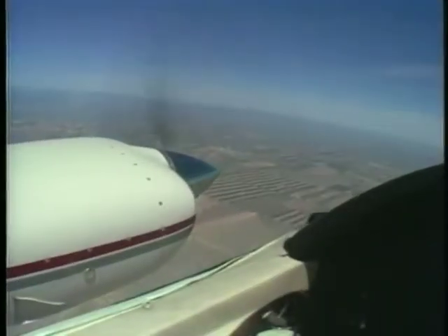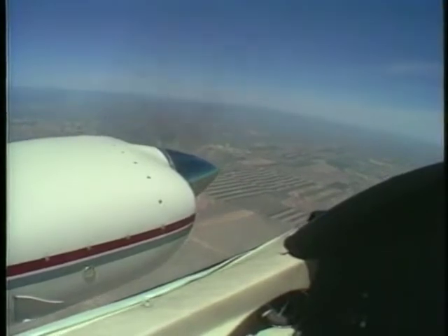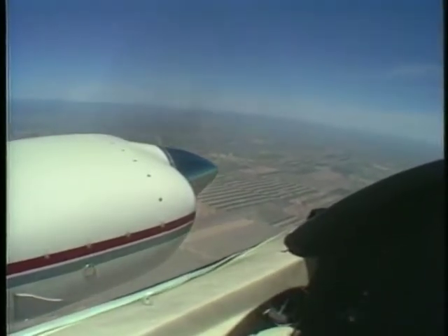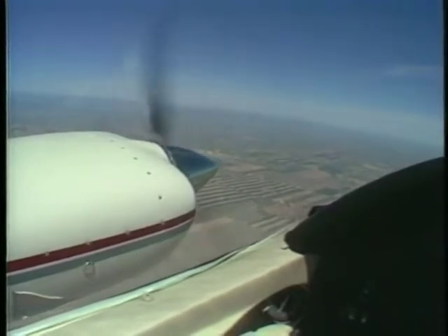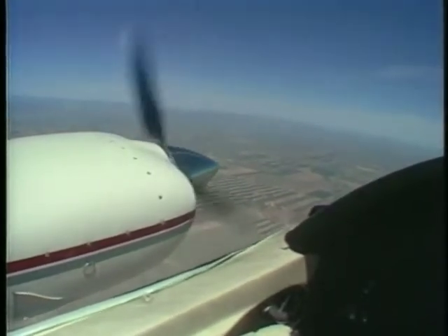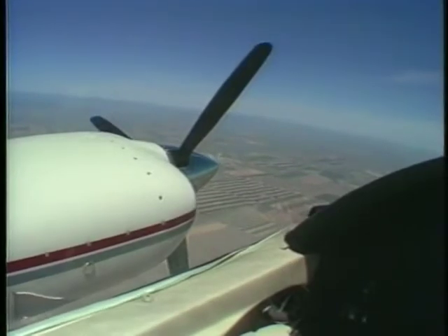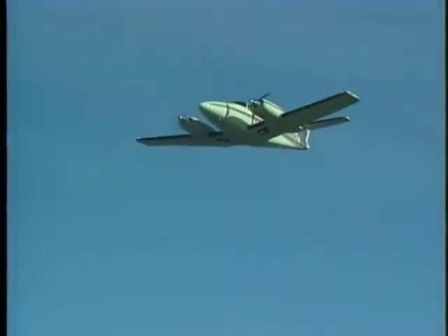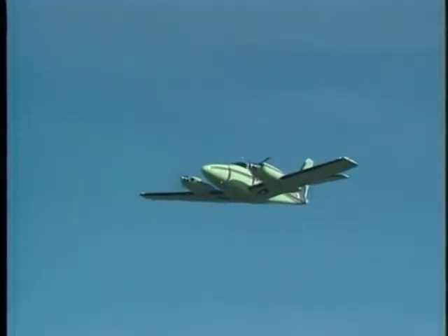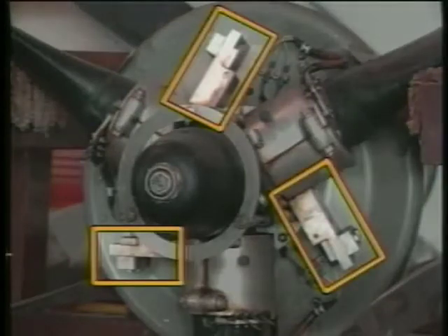Most multi-engine aircraft have what is known as featherable constant-speed propellers, which allow the pilot to rotate the propeller blades so they are nearly aligned with the relative wind. This reduces drag should an engine fail. In this system, oil pressure is used in conjunction with aerodynamic forces to decrease the pitch of the propeller blades and a set of counterweights to increase the pitch.